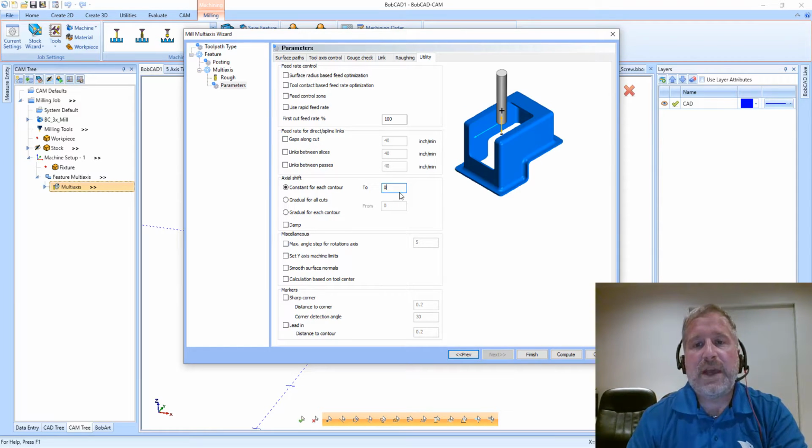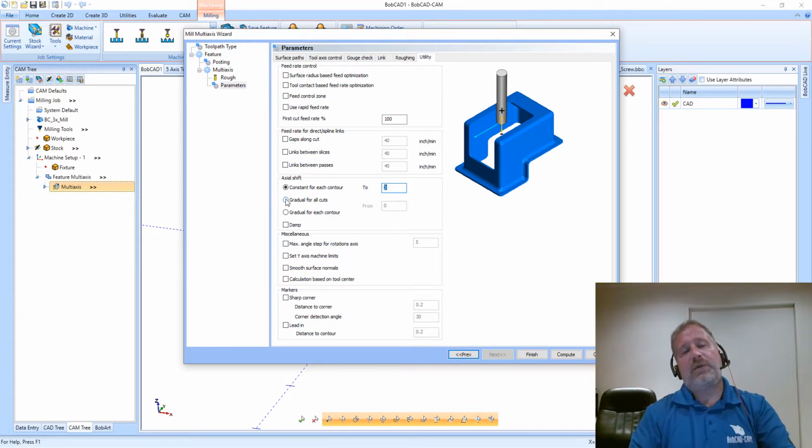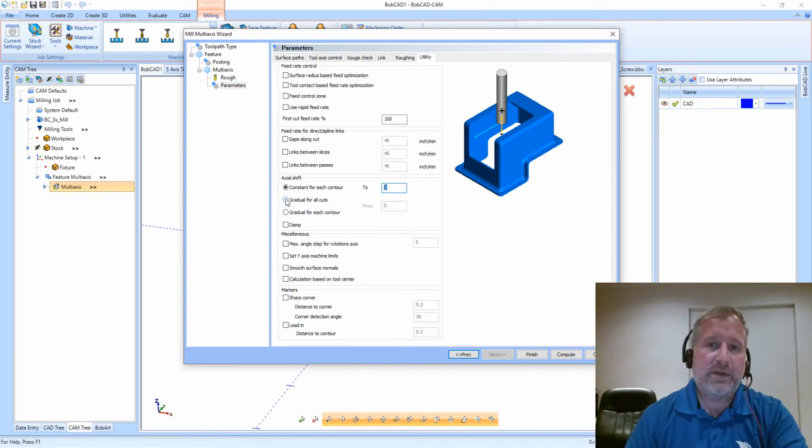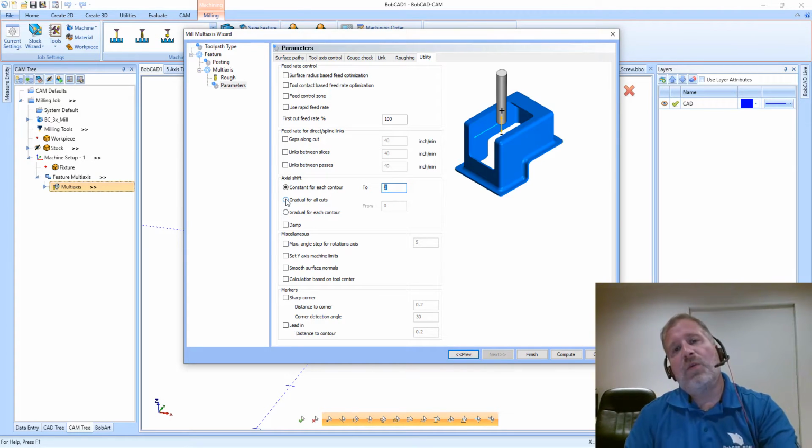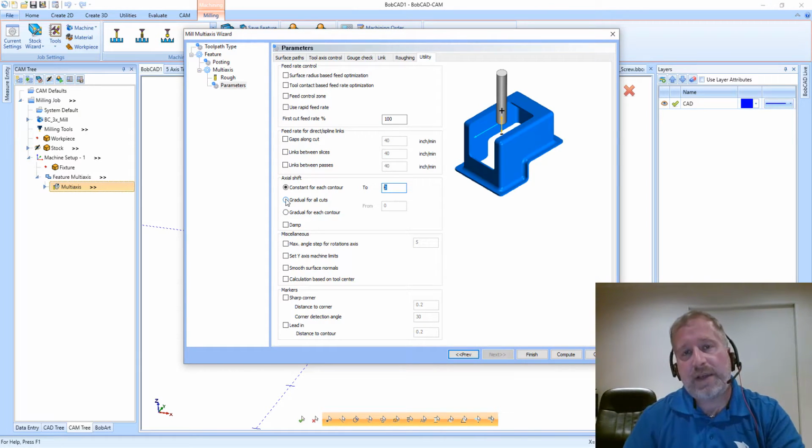You can actually drive that tool deeper beyond the bottom edge of the part and have that applied either instantly and equally across the entire path, or you can have it shift over the duration of a tool path. So let's say that we have a tool that has 2 inches of flute and we're cutting through material. The depth that we're cutting is not really all that important because we're trimming maybe 1/8 inch thick material, but I don't want that tool path to always be cutting at that same height on my tool because it's going to wear out that spot.